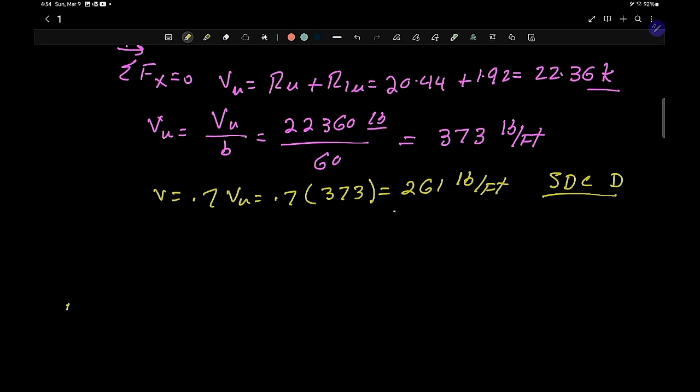Now we've got to go look up in a table, find out if we can find a sheeting and what type of nailing is going to be stronger than this. So this is basically the applied load. We like to find something with a capacity bigger than this. What I'm talking about, let me go to the PowerPoint for a second.